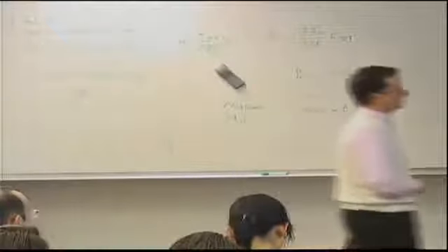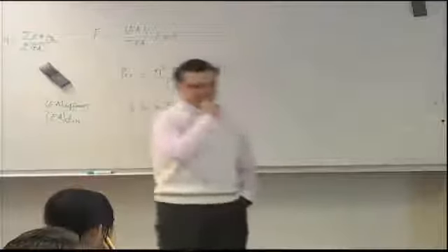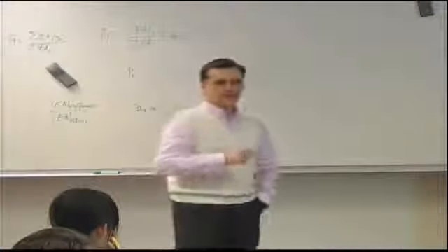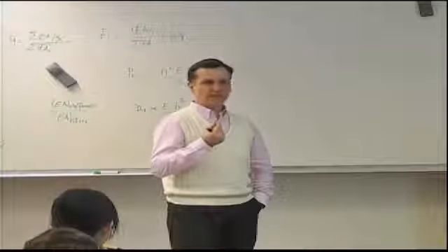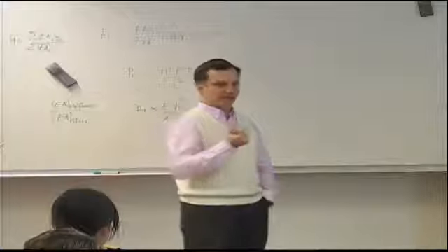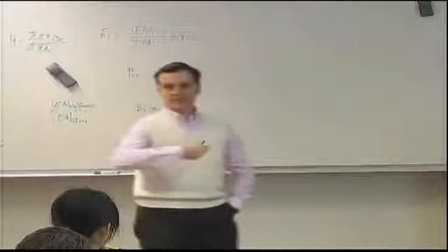And this is a straight line on a log plot, or it would be a curved line on a linear plot. I can therefore start wondering when I switch from one failure to the other. If I start from very small fastener spacing, I have crippling, and as I keep increasing the fastener spacing, then all of a sudden I will get inter-rivet buckling, and that's the one that will dominate.